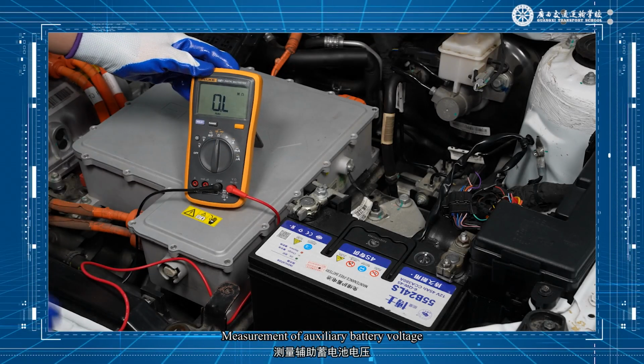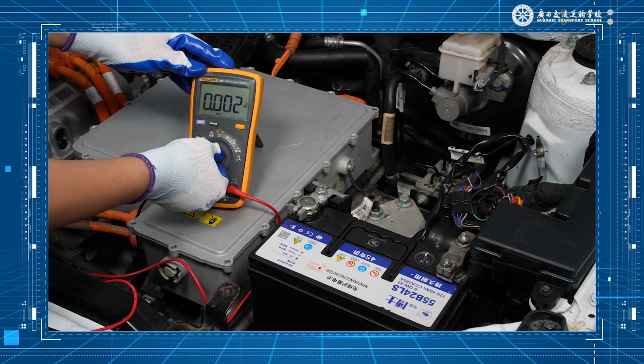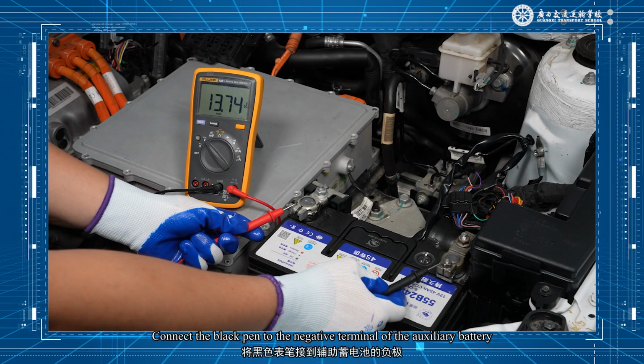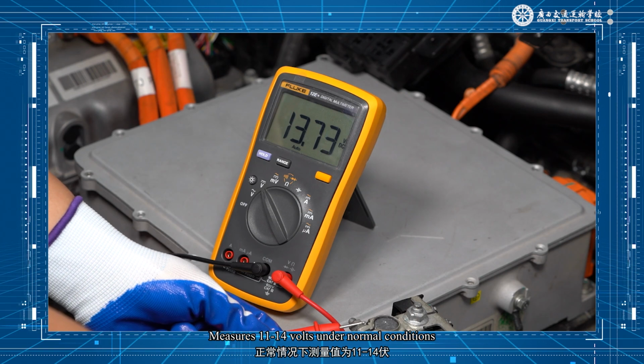Measurement of auxiliary battery voltage. Connect the red pin to the positive terminal of the auxiliary battery. Connect the black pin to the negative terminal of the auxiliary battery. Read the DC voltage value. It measures 11 to 14 volts under normal conditions.